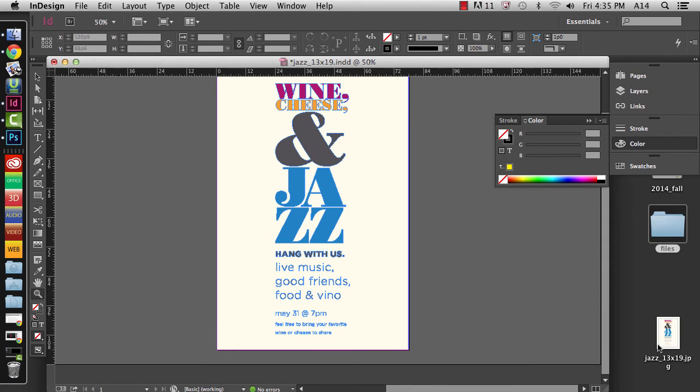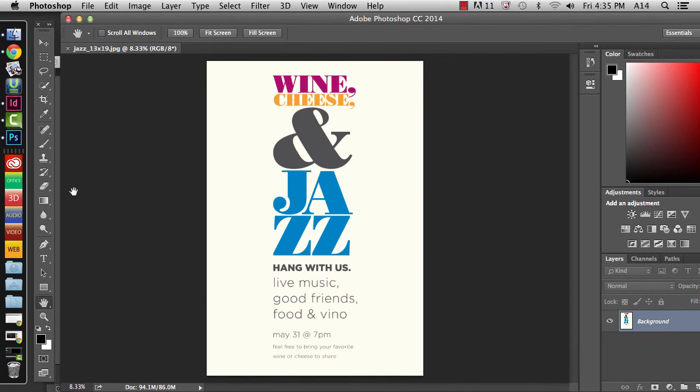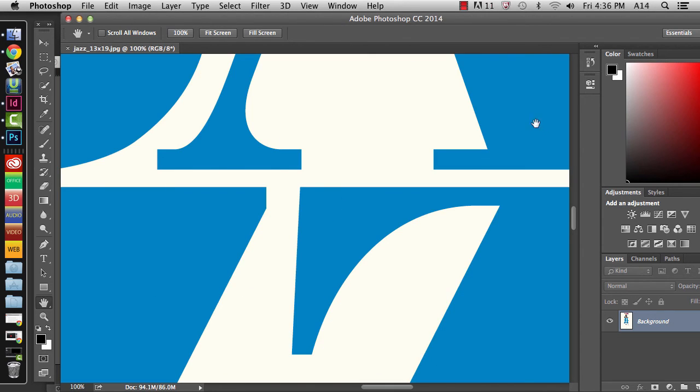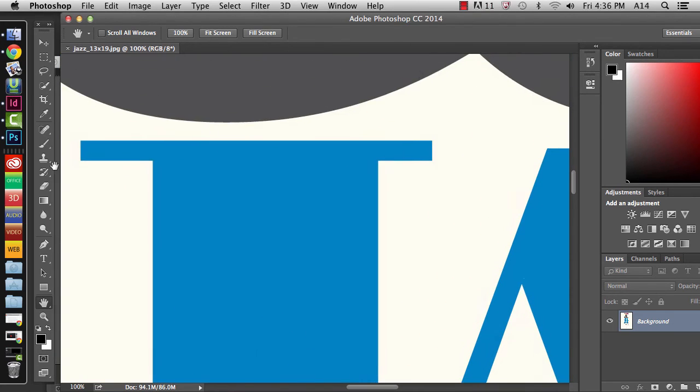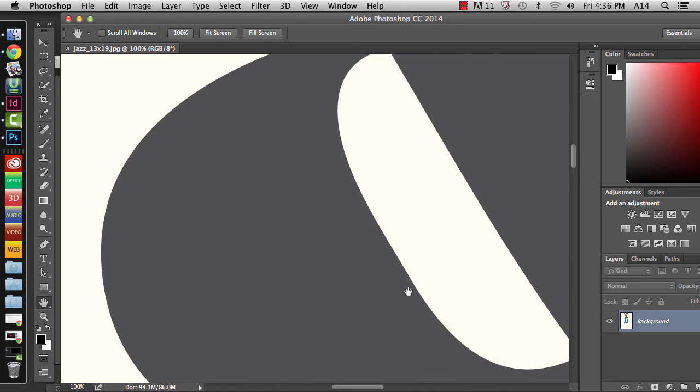And then when you're done, what you're going to see on your desktop is that picture. And now what I'd recommend is to open this in Photoshop and take a look at it and make sure it's going to look the way you expect it to. And you're not going to be looking at it at 8.33% or whatever crazy resolution or percentage it zoomed you out to. You want to not fit it to screen. You actually want to look at it at 100%, and you want to look at the quality of your vectors that got turned into raster graphics, and make sure that these lines are nice and crisp.